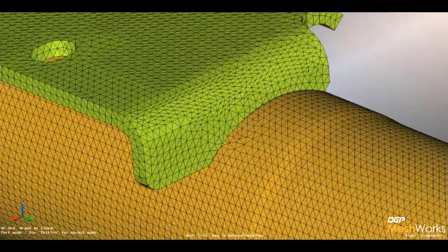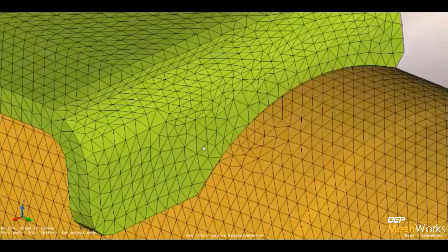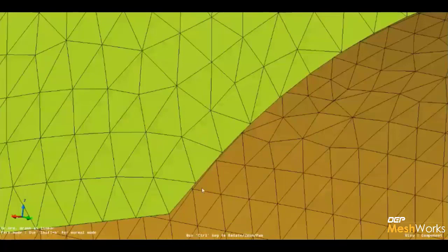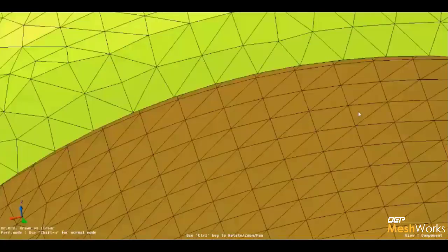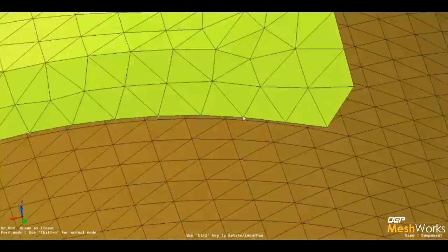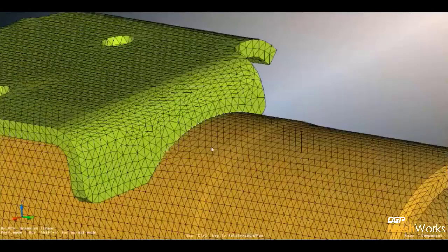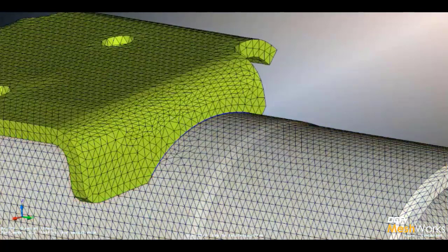I'm going into the seam welds, and here I just need to specify where my welds have to come. In this case, I'll specify a node by path, wherein I enter both the extremities, and then I select my master component and a slave component, and the type is going to be weldment.